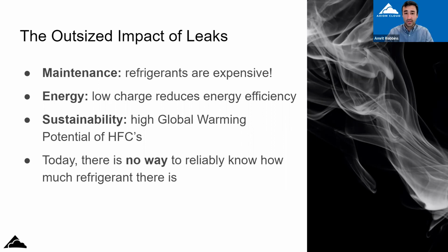And then from a sustainability perspective, obviously leaking refrigerant is really bad from a scope 2 and a scope 1 perspective. But from a scope 1 perspective, leaking refrigerant, those gases such as R22 or 404 or 407 are thousands of times more potent than CO2 from a greenhouse gas perspective. So leaking 1 pound of that might be the same as driving your car for weeks or months, let alone leaking 2,000 pounds when you dump the entire charge in a grocery store.